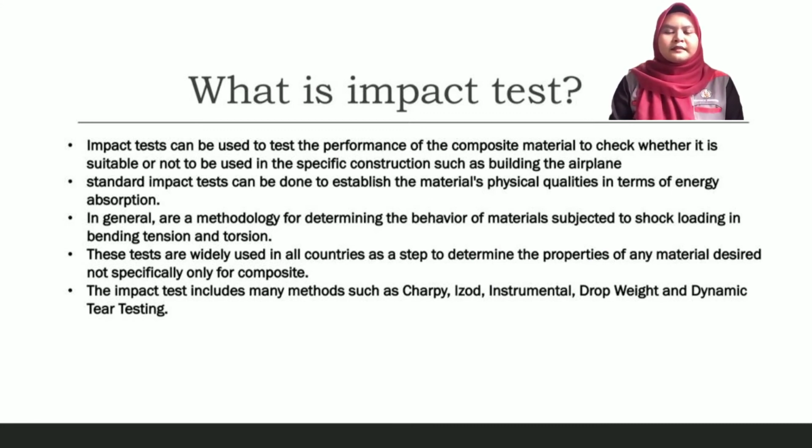In common, impact test is a technique used by engineers to determine the properties of a material. This technique has many methods to determine the behavior of the material under shock loading, which acts as a force on the material. Impact test is one of the famous methods currently used all over the nation for determining material properties, and it is not only used for composite material but also for other materials. Furthermore, impact test includes many methods such as Charpy, Izod, Drop weight and many more.